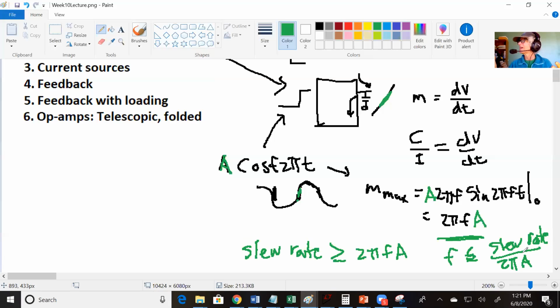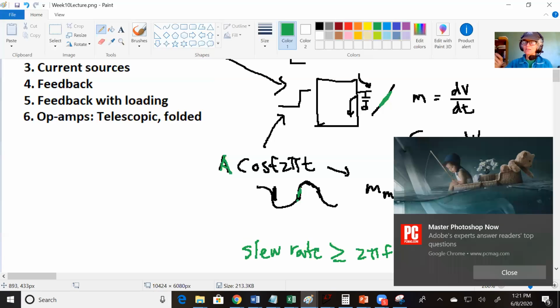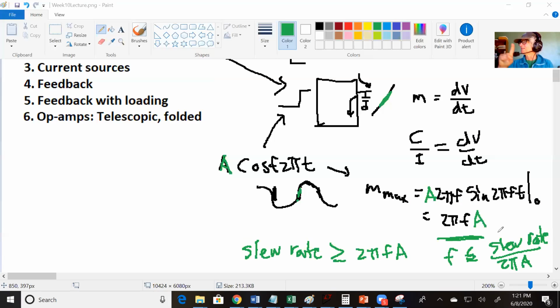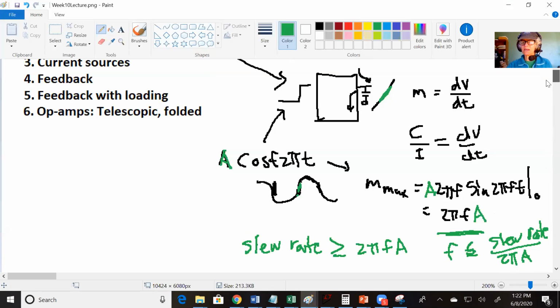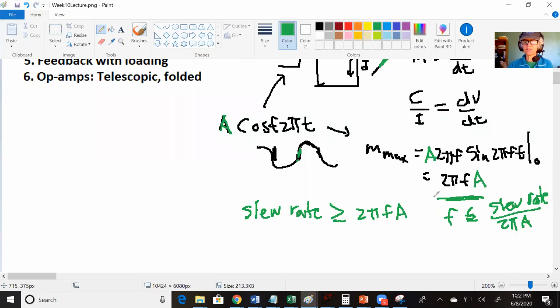You're not testing if a single frequency will work in your circuit. You've got so many frequencies, it's really hard to get information. So a sine wave is the only signal that is composed of just one frequency, and that's why it's used here to find your Fmax. This frequency right here is the maximum frequency you can run your circuit at, so it is called Fmax.